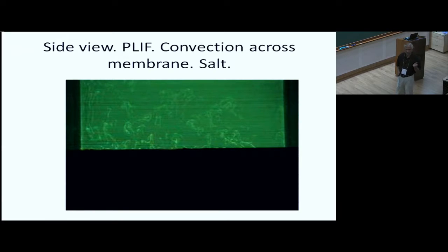So typically to increase the Prandtl number, what one does is to increase the viscosity. But here we reduce the diffusivity, which means the Rayleigh number also increases and you get high Prandtl number as well. And so this is exactly what you would see. The type of convection here is exactly like what you would have on a heated surface, except the Prandtl number is much higher.